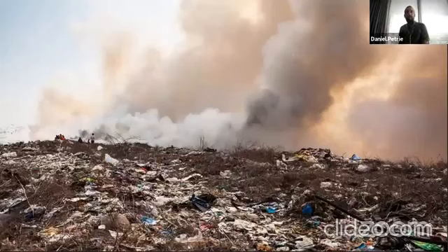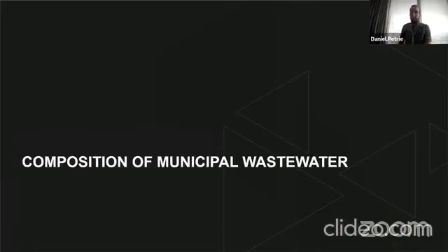If there is embodied energy in the sludge and you dispose of it in landfills, those bacteria in the landfill might break it down and start releasing methane gas, which can cause fires, can cause spontaneous combustion of a landfill, or it can escape to the atmosphere as methane gas, which is a really significant greenhouse gas. And then, of course, wherever we send the sludge, it's got to be stable enough that it won't leach contaminants and pollutants into the ground or the soil. So those are really what we're after.